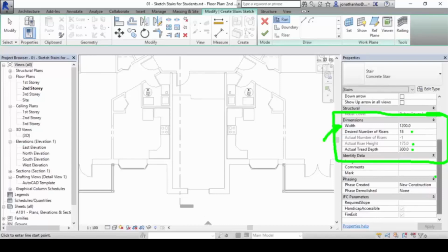Alright, and these numbers are derived from our local building control regulations. For example, the absolute minimum for the width of the staircase is actually 1160. Factoring in 40 mm from the wall, 40 mm thickness for the handrail, 1 meter clearance for walking through to and fro on the other side, another 40 for handrail, another 40 for handrail clearance from the wall.